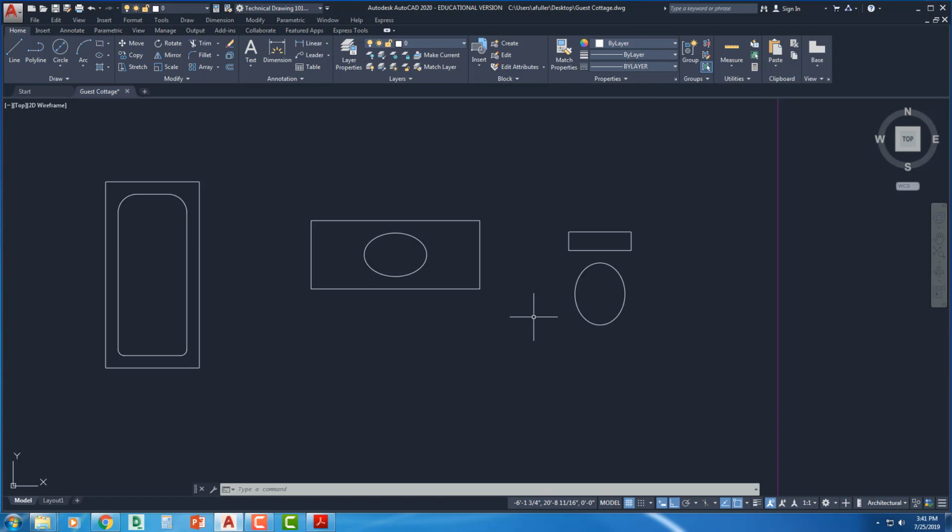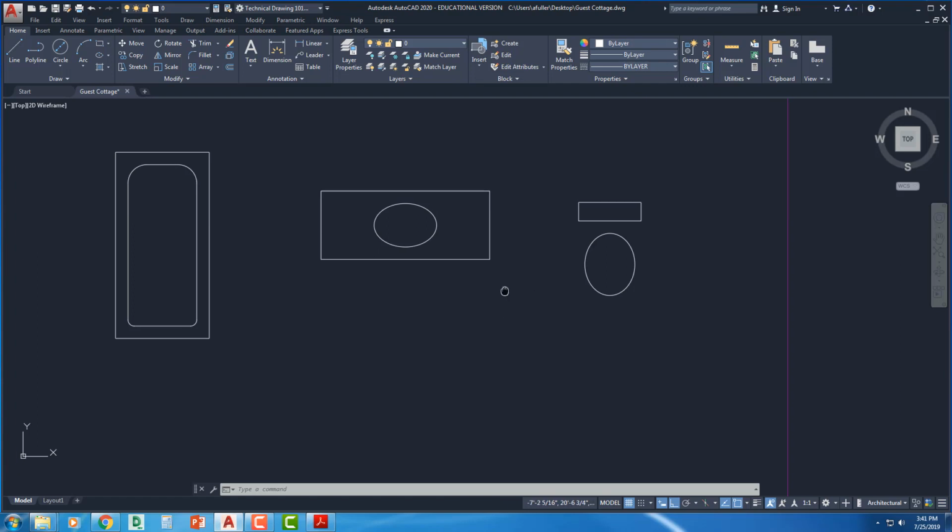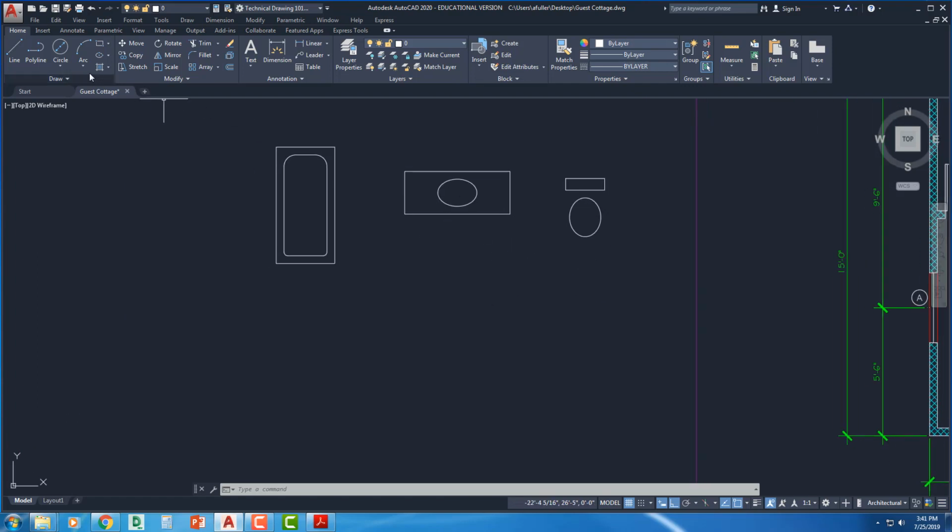I'm going to make the ceiling fan real quick. Now the ceiling fan I'll make over here. I'm going to start off with the circle diameter command. First diameter, it says, is 4 inches. The second, they're concentric, so starting at that same center point, the second one is 3 feet.